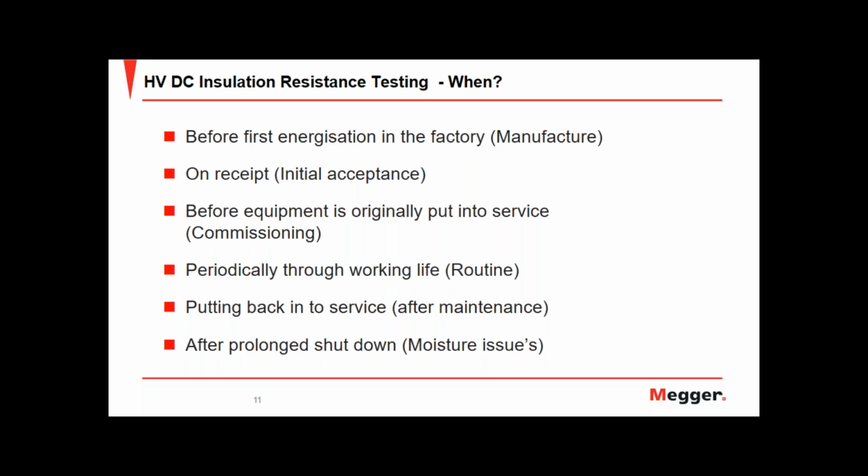Okay. So another time we would perform an IR test would be if we've had a prolonged shutdown, maybe in a factory environment where they've been shut down for up to 2 weeks. Everybody's off except for the maintenance engineers, and there'll be a team of engineers assisting them to get stuff done quickly in that 2-week period. The heating's probably likely to be off. The machines will not be operating, and moisture starts to go into some of the insulation material.